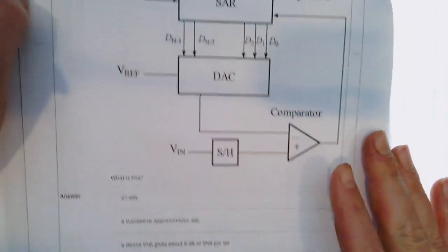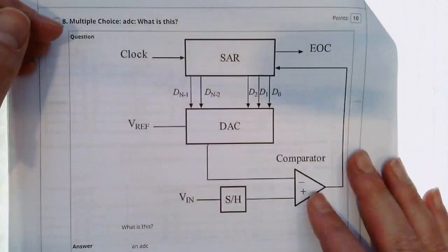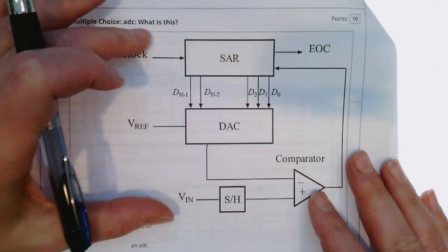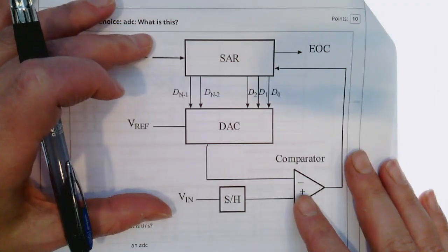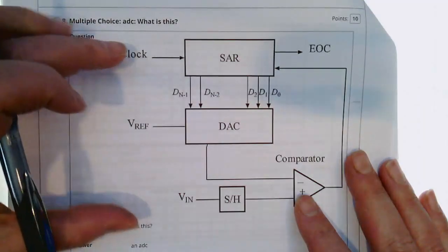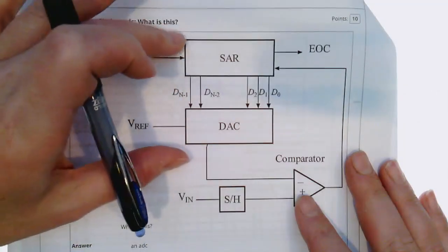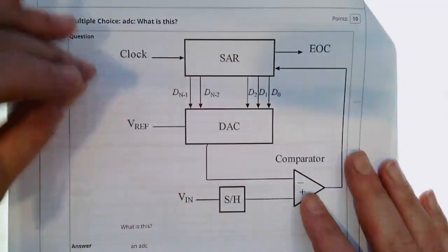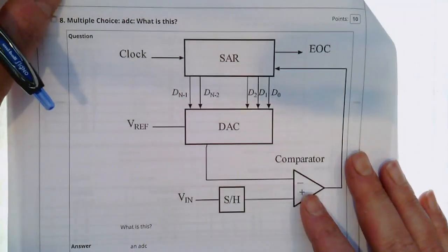Now, this is one of those things where you kind of have to read the book, but that is also an important feature that you will find built into the chip we call the Arduino Uno. So it has several inputs to a successive approximation A to D converter, so you can get analog signals into your little microcontroller. And this is a very typical sort of thing. I've built one myself just out of discrete resistors and an up-down counter, and it's very educational to do that.